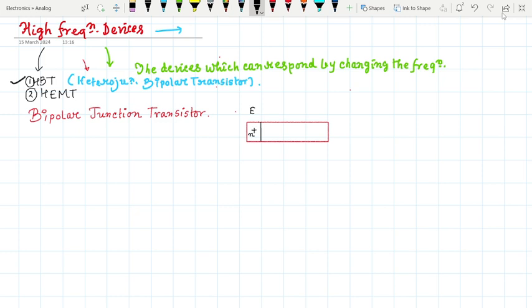Based upon these facts we can draw this. We have considered an NPN transistor. What is the circuit symbol? This is the collector, this is the emitter. To signify NPN, an arrow is given here. This is the emitter and this is the base. So this is the representation for the NPN BJT. Now we will study by this block diagram. The N plus region is the emitter; the base is made thinner and lightly doped, so we can say P minus, and thinner; and the collector is wider and moderately doped, so we do not signify any plus or minus here.